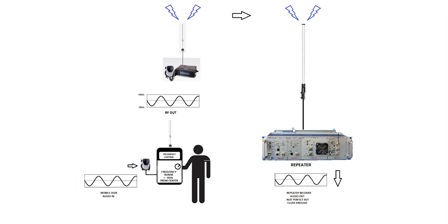What we do is a little trick where we inject a steady signal into that varying RF signal coming in, and we produce what's called an IF, an intermediate frequency, that we then mix again in a process called superheterodyne, and that's how we eventually recover our audio out. But the audio that comes out is a reproduction of the original audio going in. It is not the actual audio.